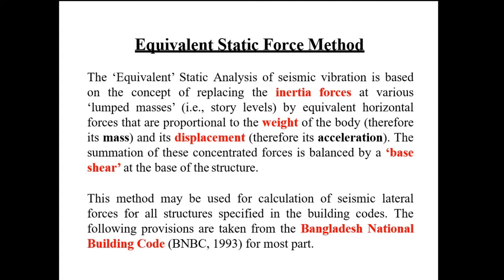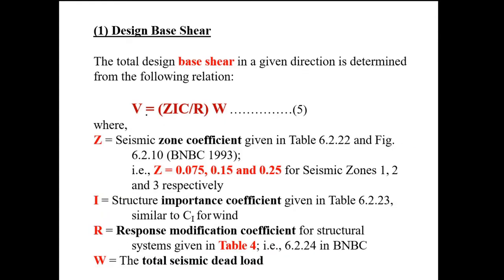And here we will be following the BNBC guideline as well. So firstly, let us know about the base shear. Base shear is simply the summation of the total inertia force that arises from the body of a structure. So if a structural element is created here, so here we can see a structure.